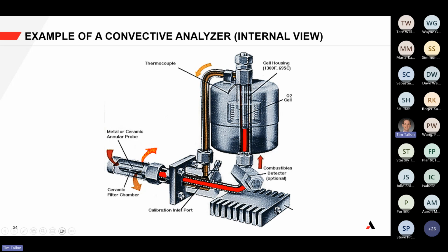So this is the inner probe inside the filter, and the outer probe, the outer annulus, vents out to the atmosphere. So it's a unique inner-outer probe design, and some of the nuances of it actually play into the speed of response based off of the pitot tube effect and the difference of pressure and velocity. The inner probe is inside the outer probe, and the filter's at the back of that.